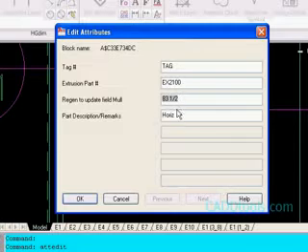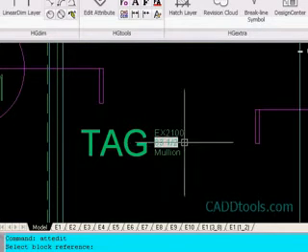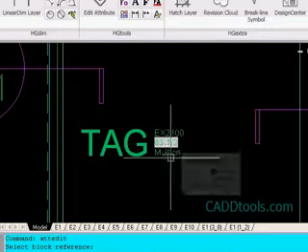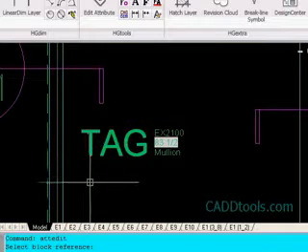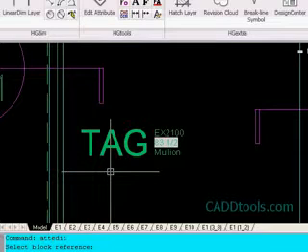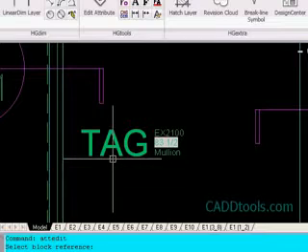This will be in my sample CAD file, and this is a storefront project, so the jamb mullion and the intermediate mullion are the same, so I will just call this a mullion. So then the data is in there: the extrusion number, the part length, and a description. Later on, the tag information will be imported back into AutoCAD after you've manipulated it with whatever optimizer you want to use after you extract the data.